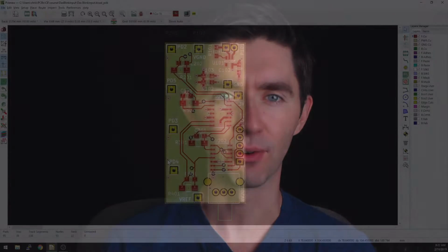Today we're going to be talking about using 4-layer boards and hotkeys. I think I've alluded to this in past videos, specifically when I was taking the board we're going to show you here from 2 to 4-layer, but I really like having a specific set of hotkeys when I'm doing a 4-layer layout, and I kind of carry that over to other things I do. So I reset it for if it's a 2-layer board or 4-layer board, whatever. So let's take a quick look at how to change around your hotkeys in general, and then how to do it for a 4-layer board.